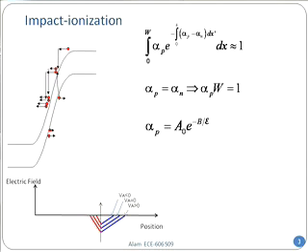Okay. Now, if that is the case, what electric field should I put in? Well, if I solve the diode equation correctly, then you can see the blue and the red triangles depending on various reverse biases. I can always calculate that. Do you remember? Depletion approximation, the charges, and the triangles that we created. So I can always create that. And I realize that the maximum electric field will be essentially, I can put the E max in place of E, the electric field E, and calculate alpha.